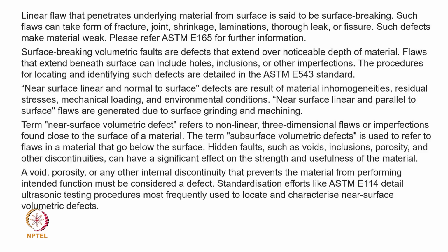So, if I want to tell in my own words, we basically have 6 kinds of cracks. We say the linear flaw, that is what has been shown. A linear flaw that penetrates the underlying material, maybe there is a vertical depth. If there is only a kind of scratch, it does not have a depth, then we do not have to worry that much. But if it has some sort of crack dividing the surface, right, then a linear flaw that penetrates the underlying material from a surface is said to be a surface breaking linear flaw.